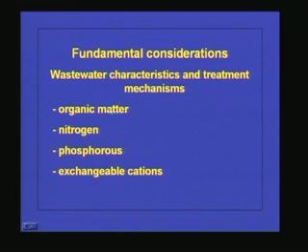And what are the fundamental considerations when we go for land treatment? The wastewater characteristics and the treatment mechanisms are very, very important. For example, the organic matter present in the effluent will be utilized by the microorganisms present in the soil.